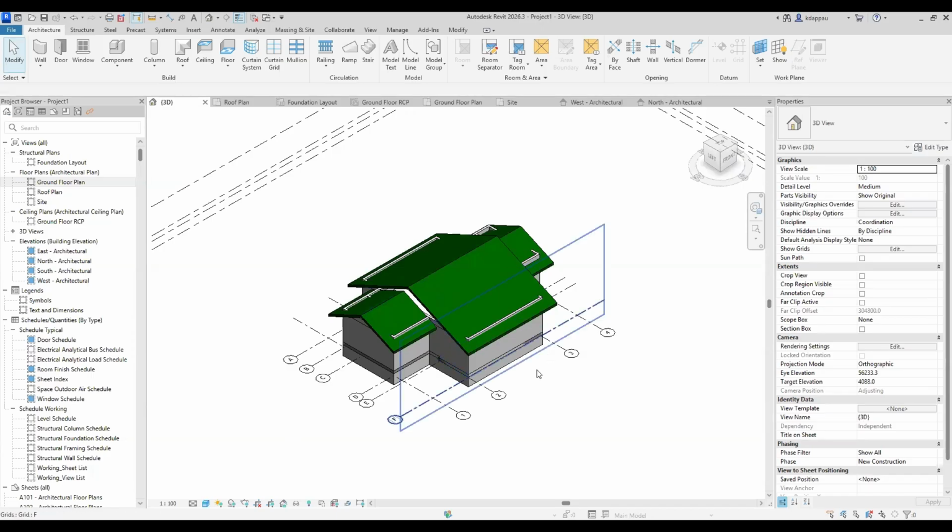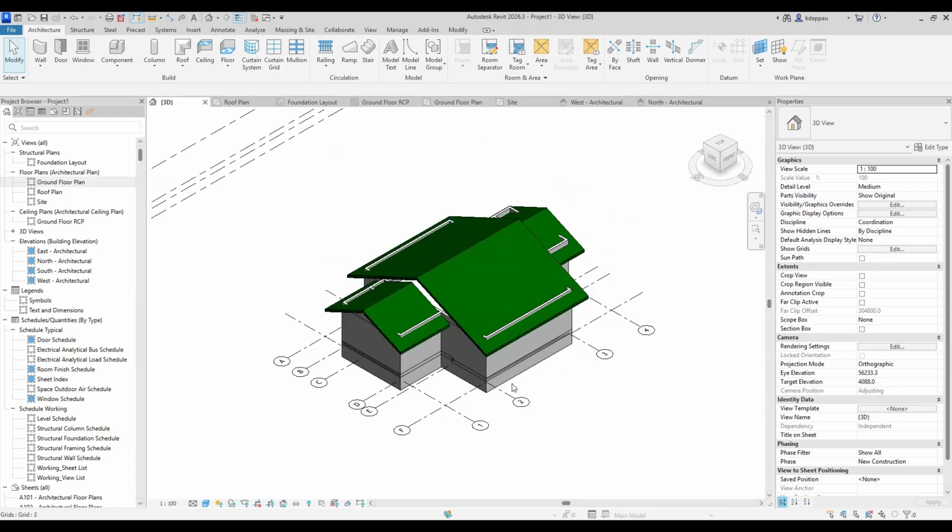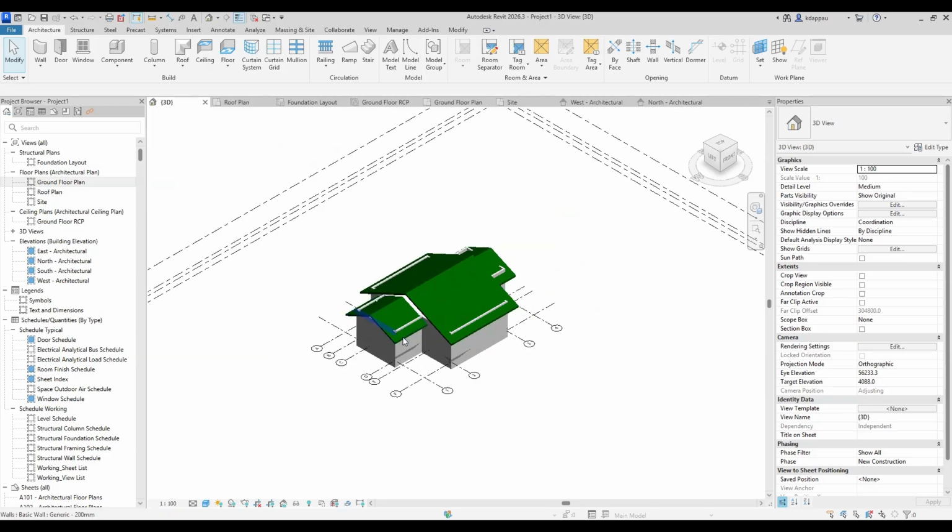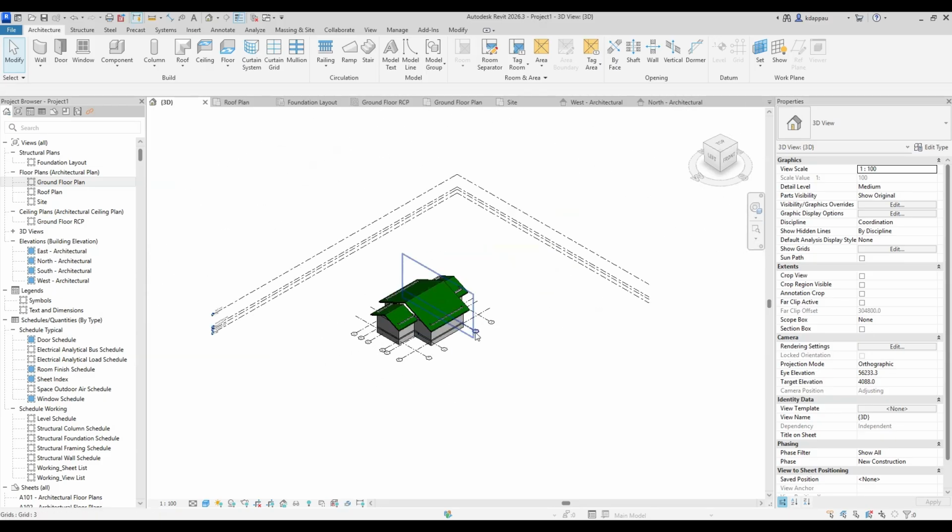So me, when I get a form like this, the next thing that I do is make sure that I prepare all the sheets that I need, prepare all the views that I need, and then put them on the what? On the sheet. So that I know that I'm working with 6 sheets, 10 sheets, 20 sheets. Then later on, I'll come back and start fine-tuning the model. Any changes that I make to the model, all of them will be updated on the what? On the sheet.